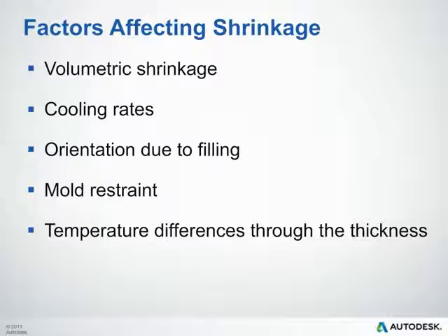There are several factors that can affect shrinkage. They are volumetric shrinkage, your cooling rates, orientation due to filling, your mold restraint, as well as temperature differences through the thickness of your part.